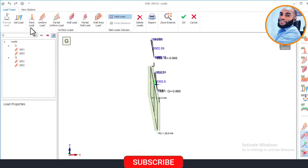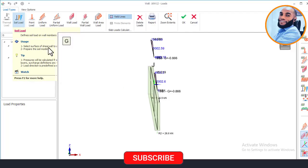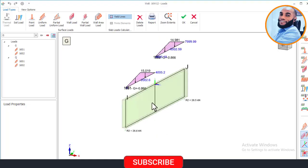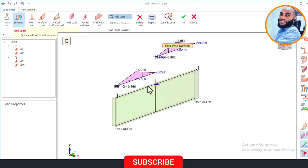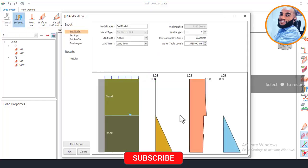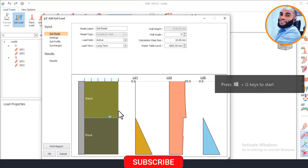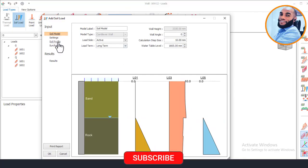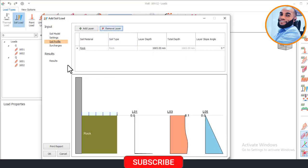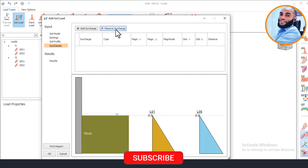Although I can still use this, what I will quickly do is go and remove the soils from the wall. If I want to use this place to apply my load, I will click on this place and then click on this wall here. I will now see this add soil load parameter. Since there is no soil at the back, I will quickly come here first and delete my soil layer. You can see that the soil is off, and I'll delete my surcharge. There is no surcharge coefficient. I'll delete all that.